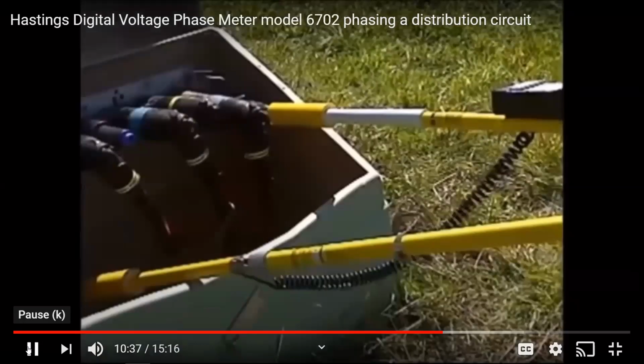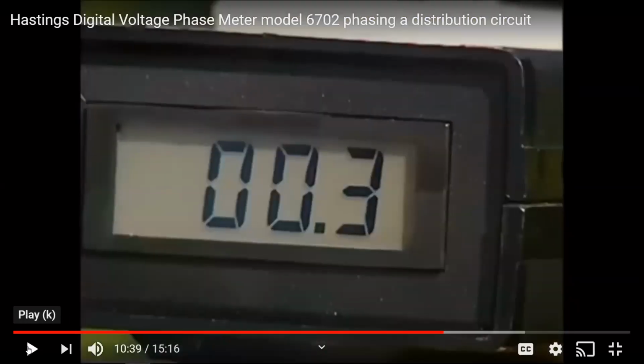You need to do this. Now, they tested the first cable. They didn't do this. My company made it mandatory that every time you tested a cable, regardless of the condition of the cable, you always grounded the cable and your sticks. That's what they're doing here. They just reversed the sticks to the feed, and they're taking the cable itself and they're going to ground with the other stick. Now, you notice they're not testing anymore, and they're touching the sticks to ground.